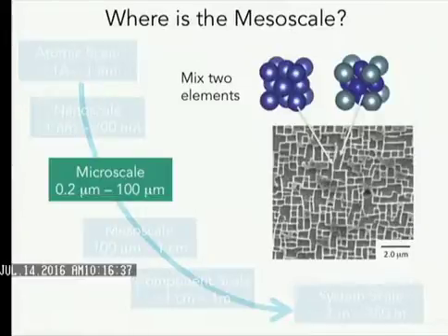And what I show here is, well, now we've got 2 elements, but thermodynamically, those 2 elements wish to form 2 different crystal structures. And this is really sort of at the root of all of the work that people have done to strengthen materials. And so we find out ways to control the mixtures of elements such that we form multiple phases, and we control their distribution and size. And that's how we get steel and nickel-based alloys and titanium, and there are also analogs in polymers where you have basically mixes of phases that allow you to control properties.